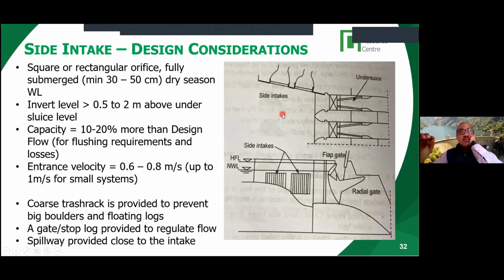Now, the important design consideration when you design a side intake is to make sure there is water level above the intake.